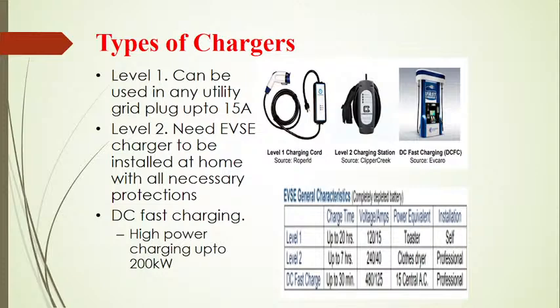Coming to level 2, a level 2 charger will take up to 7 hours, and the voltage is higher compared to level 1. It will take 240 volts and 40 amperes.